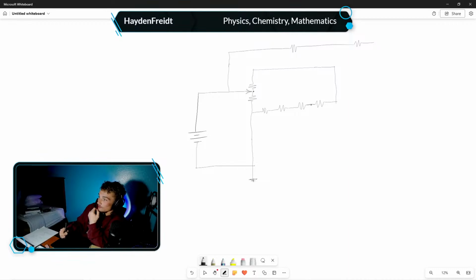When I reach a certain level of voltage, I'm going to have a particular magnitude of current flowing through these resistors here, which is going to activate the gates or the base of my transistors, which will close the circuit to the LEDs and light them up and supply them.